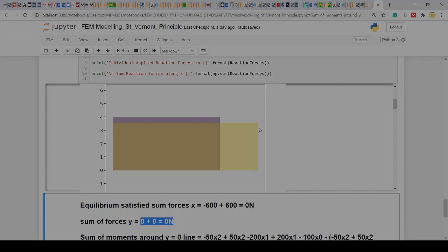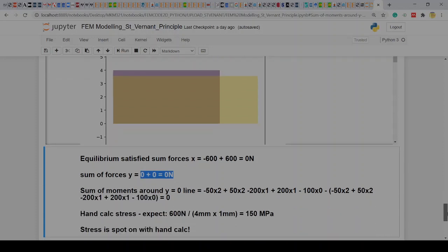But hopefully this gives you a very good idea of the benefits and key insights of Saint-Venant's principle: as long as we look sufficiently far away from where we made a boundary condition simplification, things will be accurate, as accurate as if we had taken great care at modeling that very accurately.